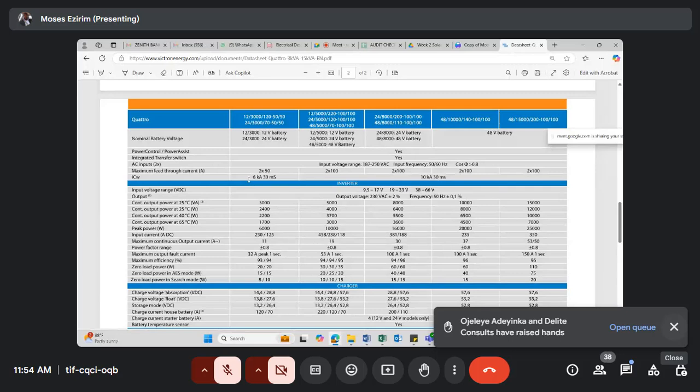Even if you check their data, if you check their dashboard, for example Victron dashboard, you will see the stage: the bulk stage, absorption and float. At the float stage, the battery is already full. And remember, even if a battery is full and you're not using it, it will go down again. I'm sure you know that. Yes, that's the self-discharge of a battery. So that's the essence of that float, that trickle. It will keep trickling on it. All right. So that's that.